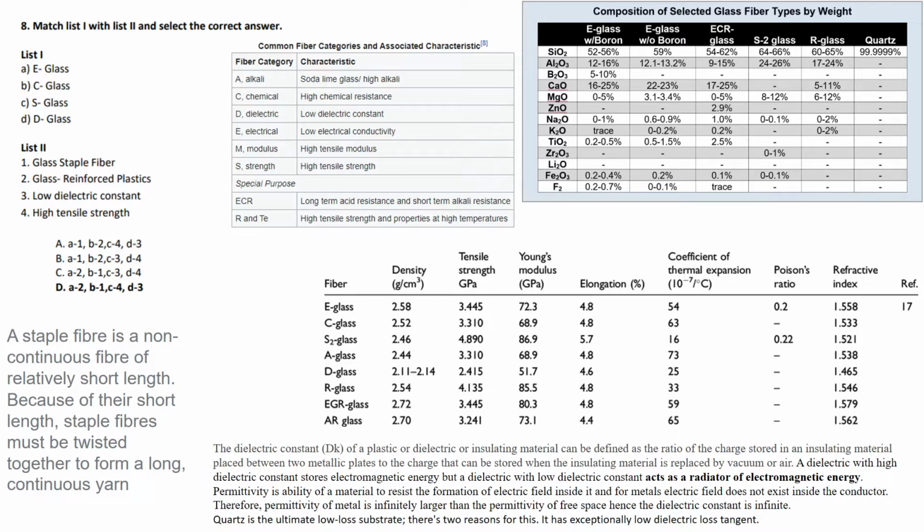Yeah. So E-glass is very commonly used, and its cost is also less compared to the rest of the glass fibers. So you can see E-glass actually doesn't have a lot of modulus and strength, it lies somewhere in between. If you want a composite which will have a very high performance in terms of its tensile strength, for example, you're trying to make ropes of bridges which will only have strengths in its longitudinal directions, like you'll apply force from both of these ends and there would be a continuous composite made out of S glass fiber with